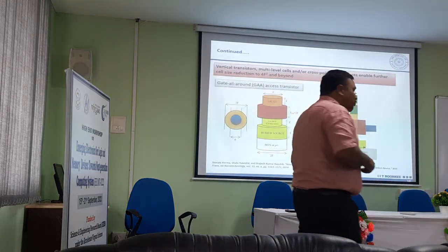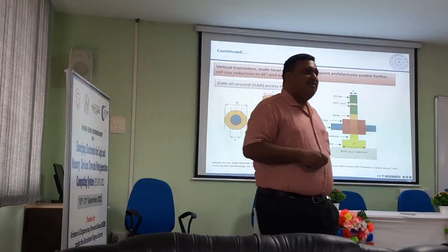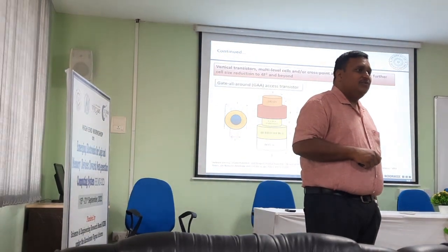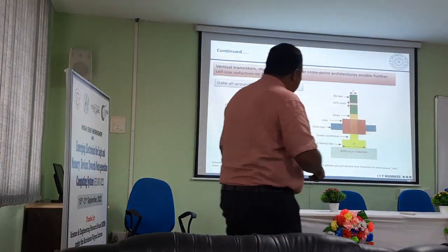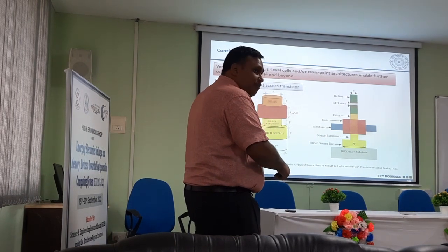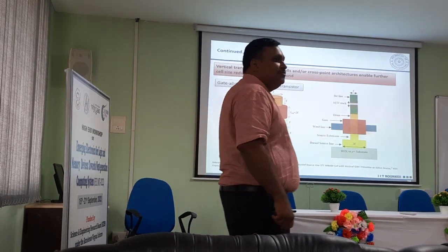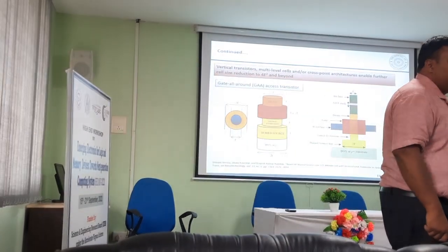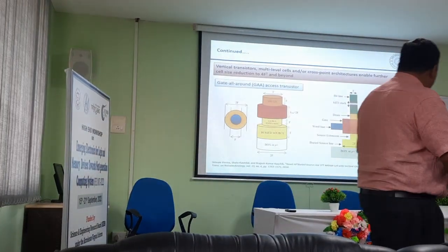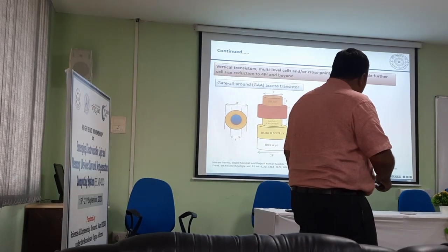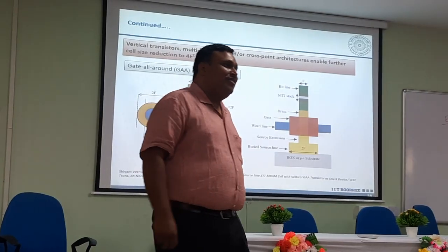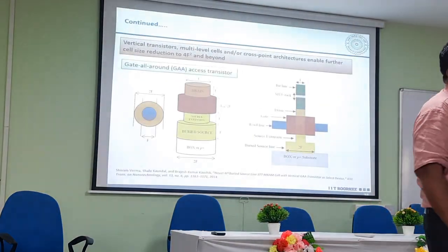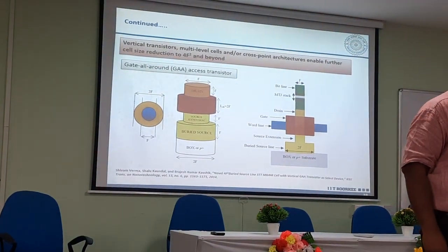Now the other part of the question is, can we realize 3D circuits or 3D designs? Yes, we can do it. The only thing is that you have to run a metal layer below the substrate also. That will be the baseline for the bottom layer, because you need to run all those source extensions below this. This was one of the important questions which we had to handle with the reviewer for this paper.